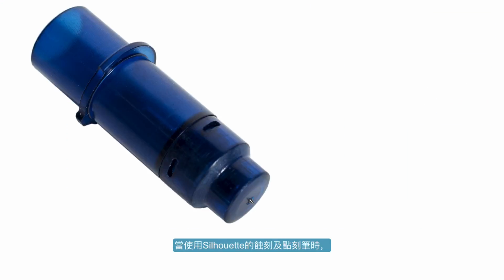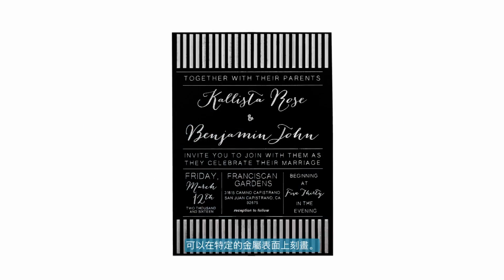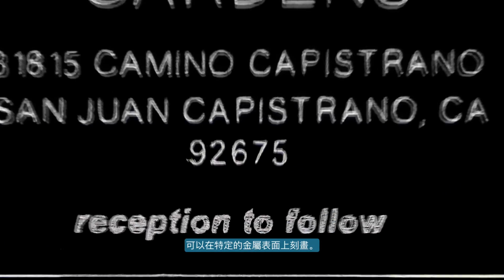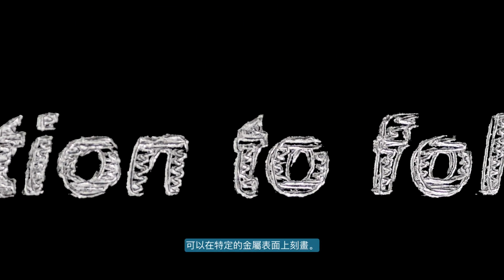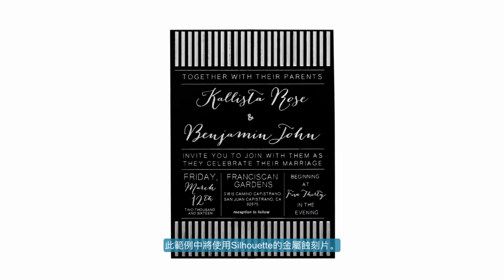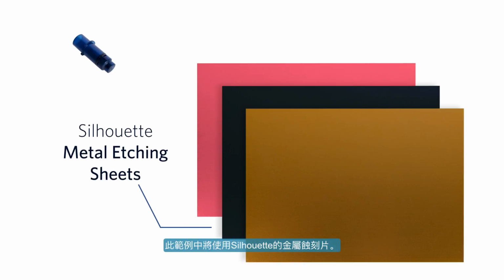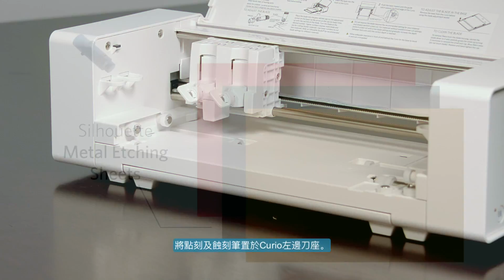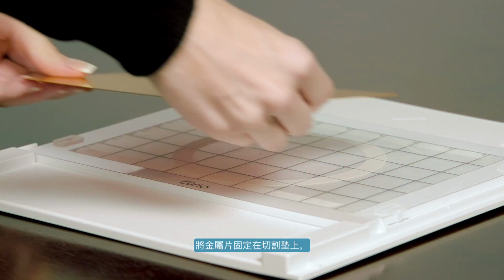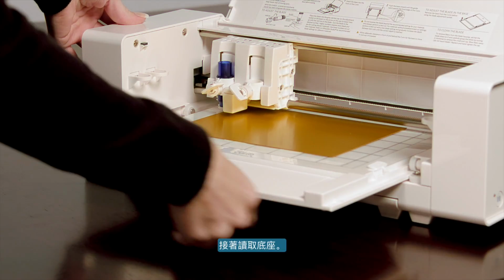When using Silhouette's stippling and etching tool with your Silhouette CURIO, you can etch designs onto select metal surfaces. In this example, we will use Silhouette brand metal etching sheets. Place the stippling and etching tool into the CURIO's left tool holder. Place the metal sheet onto the cutting mat, then load the base into the CURIO.